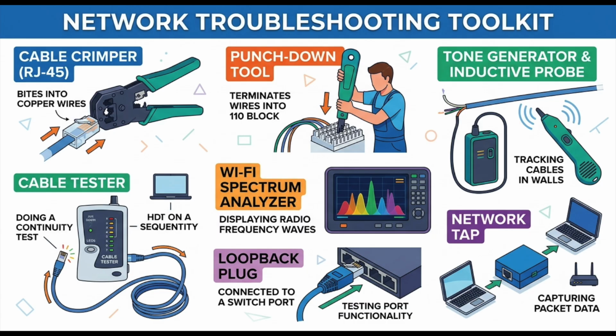It is. But if a technician untwists too much wire before punching it down, that unshielded segment acts like an antenna. It absorbs interference that can't be mathematically canceled out. Man, it's a wild example of how purely analog physics, like the literal geometric shape of a twisted copper wire, can completely dictate the speed and reliability of our high-speed digital reality. A single sloppy punchdown can degrade an entire gigabit connection.